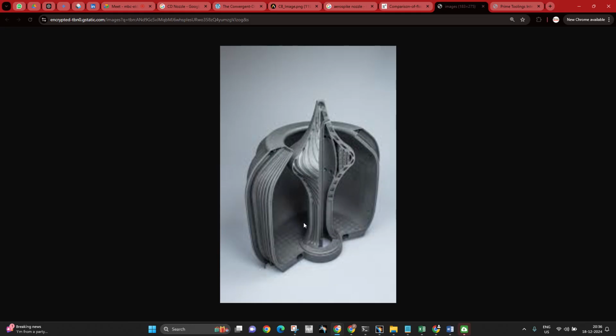The thing is, it generates a Coanda effect at the surface curvature over here, where it makes the flow stick towards the convex surface, and as it goes outside, it sticks on the spike. It is aerodynamically efficient, where it generates a lower pressure zone. When it generates a lower pressure zone at the spike end, the higher pressure environment area will get sucked in. Since there is a lower pressure zone at the high velocity area, the surrounding air pressure will get sucked in. It mixes along with the flow to concentrate the thrust.